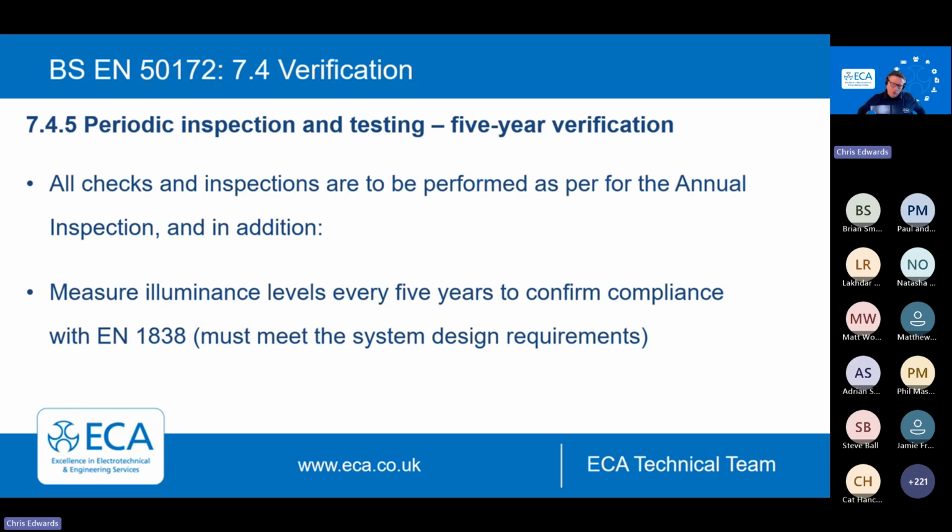This one is new, 5-year verification, and I'm going to just hang on it for a couple of minutes. 5-year verification is new, and it's mentioned in all 3 standards. And the point is that every so often, we need to verify. We need to prove that our system is working as we want it to work. Now, it's quite clear in the standards that it must meet the system design requirements. But the problem is, of course, as we know, you're probably not going to have the initial design data, in which case you default to the requirements of the latest standard.